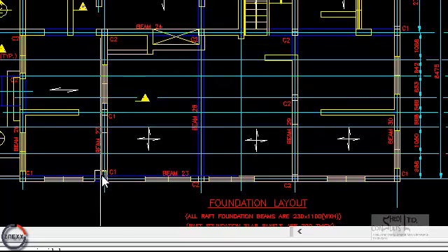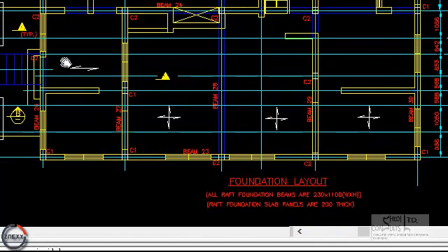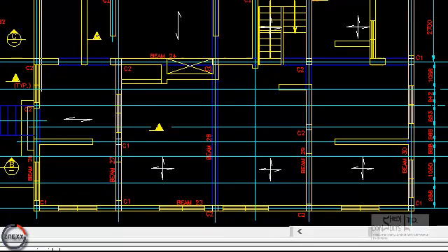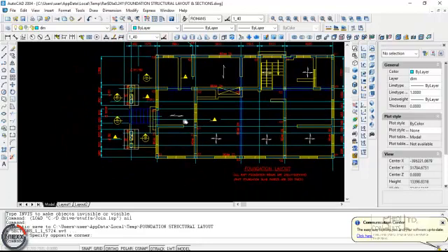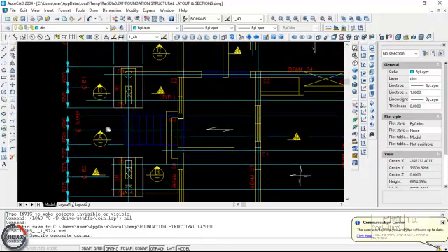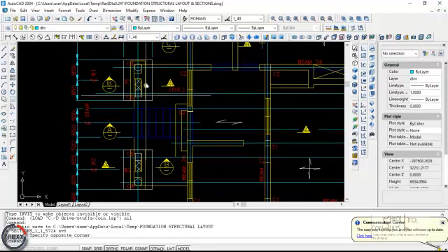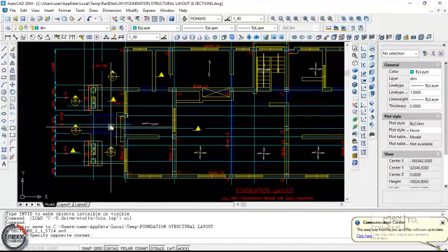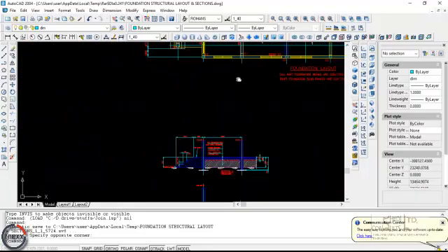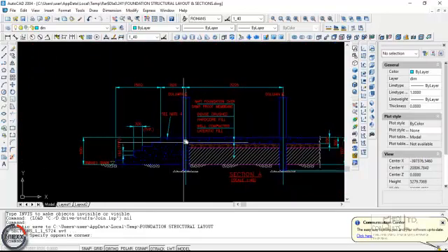This is the superposition of the ground floor architectural layout on the proposed structural layout. So you could see the location of the ground beams. You have a ground beam on grid B, grid C prime, E prime, and F prime. So this is the approach to the structure. This is the foundation for the approach location. Those are the columns. So that's the staircase. Look at section A. Section A shows you what's going on there. That's the staircase, and those are the columns.